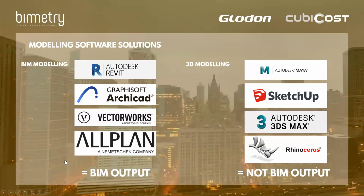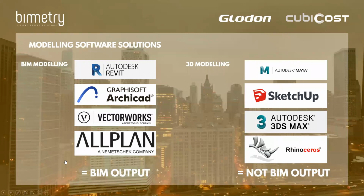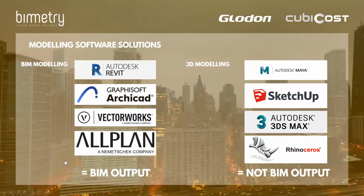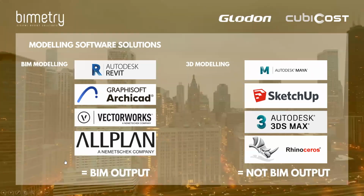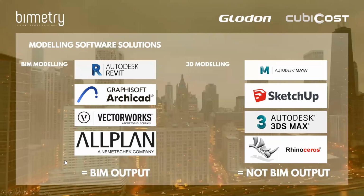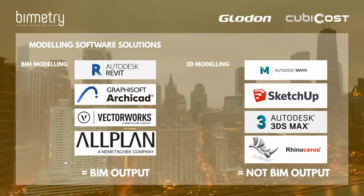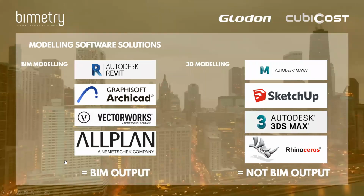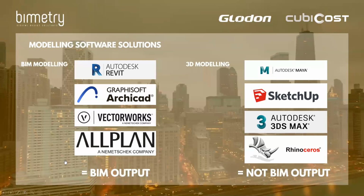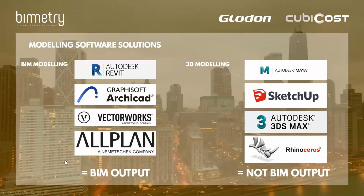You can reference the 3D geometry, for example, in Cubicost, but you might not be able to extract the quantities that you usually would be able to extract from Revit. The reason is that, for example, panels won't be recognized as panels and columns won't be recognized as structural members. So it is very hard to schedule the quantities in different spreadsheets as you would usually do from Revit.